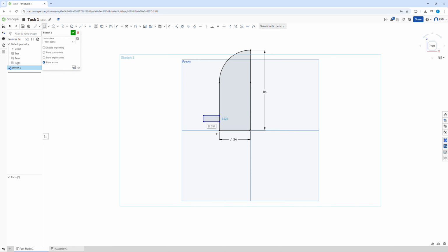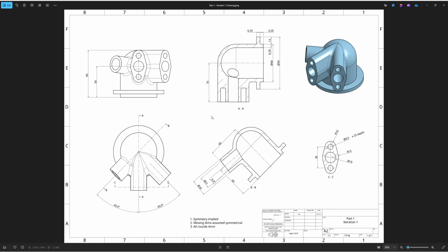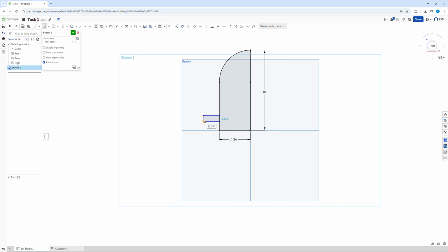Okay, we've then got this rectangular bit that sticks out, so we can add this on. I think if we go back to our dimensions, we've got this as 6.35, 6.35, and it's 13 out. So we can go and make this 13. We can make this part, nope, D for dimension. What's that? Ooh, not bad, 6.35, press enter, and we want this from here to also be 6.35. That looks good. We have also recognized that this is hollow, so we're going to just offset this.